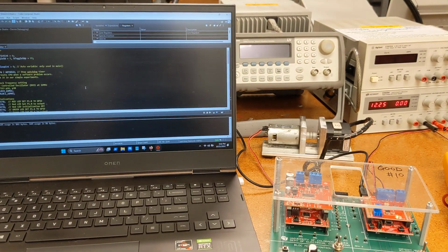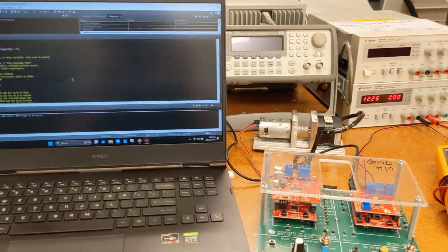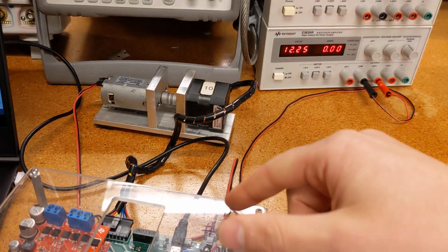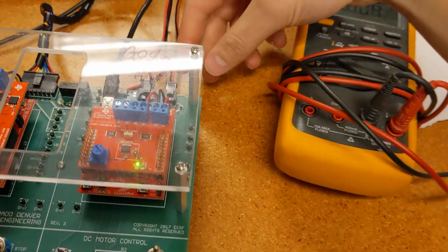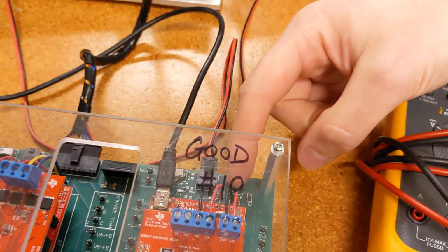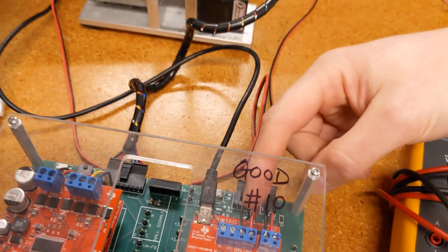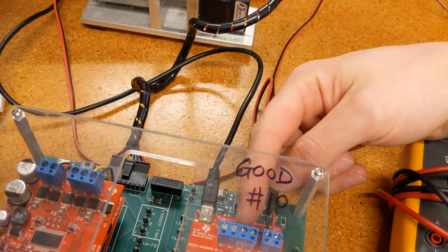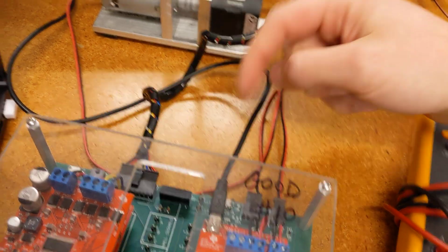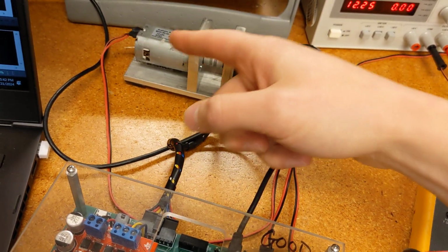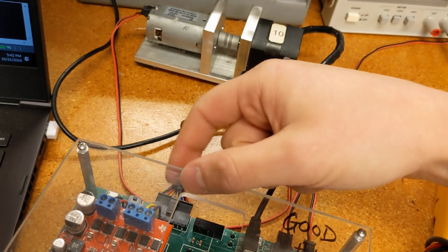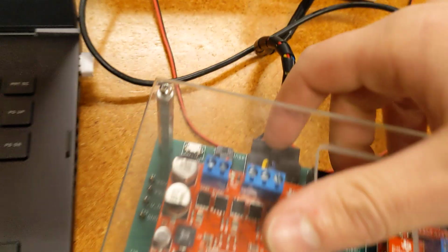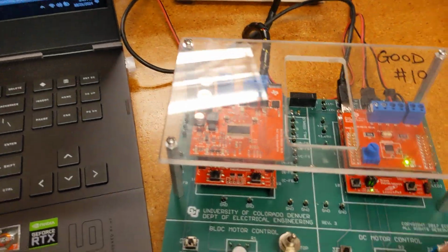All right, we have our DC motor session 3. Coming over here, we got 12 volts coming out, going into our motor supply. This then just gets fed right up into this. This connects to our analog output, A channel, A2, A1, of the motor itself. This is our motor. That's our load. The load does have to be connected, that way everything closes a circuit. It's a closed circuit.